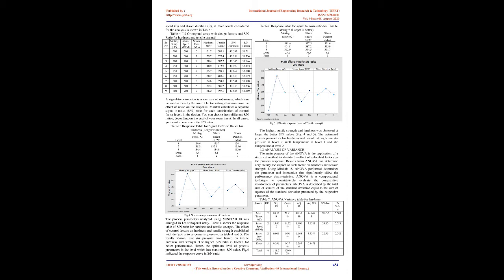The total degrees of freedom for 3 parameters in each of 3 levels are 6. Then, a 3-level orthogonal array, L9 (3^3), with 9 experimental runs, degrees of freedom equals 9 minus 1 equals 8, is selected for the present research. Orthogonal array, OA, is nothing but the shortest possible matrix of combinations in which all the parameters are varied at the same time and their effect and performance interactions are studied simultaneously.